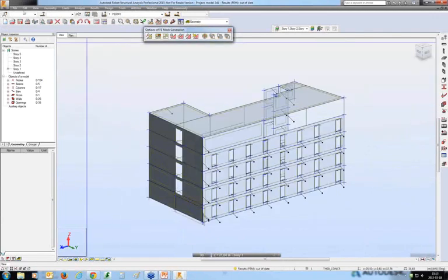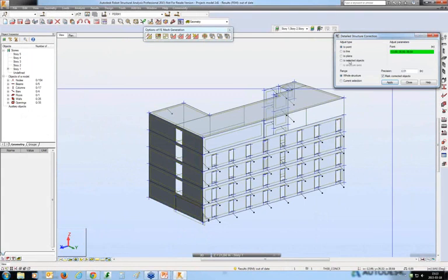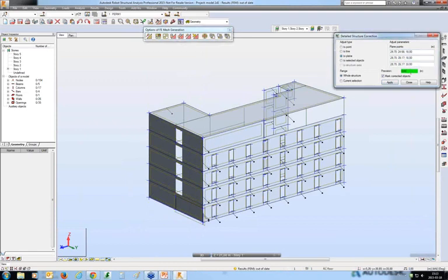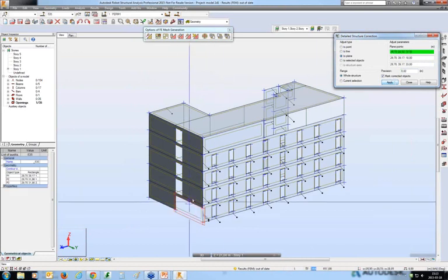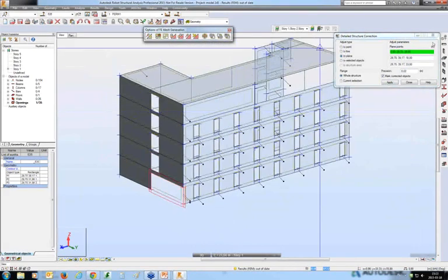Running the detailed correction option, I should indicate the plane as I did previously, but I should also enter the right precision. This time it is 2 centimeters, slightly more than the error that I made in the geometry.